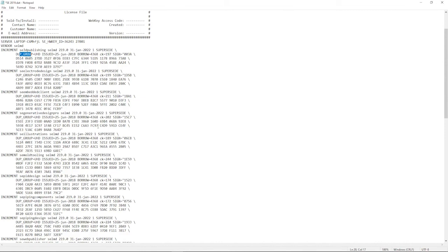So customers that had Solid Edge 2019 and were moving to 2020, if they didn't have that restriction method put in, the license file that would be generated was just a temp file that would expire after a couple days. So then we would need to go in and put in a composite host ID, the number used to restrict the license file to a server, so that it was restricted. So that's the kinds of things you can take away from your license file.